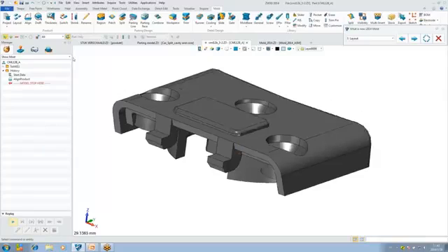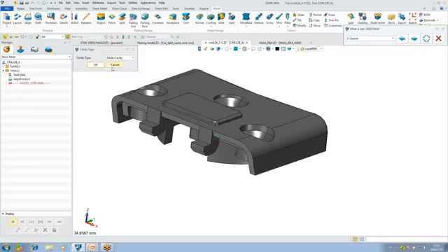Here we will use the new project command in ZW3D. Compared to the previous version, you will see that at the beginning, ZW3D will ask you to select which kind of cavity type you want to create. Select multi-cavity, click OK, and give it a project name. Look at the shrinkage input field. This is the value related to the value in the shrinkage command, so if you set it here, the value will also be changed in the shrinkage command. Click OK.